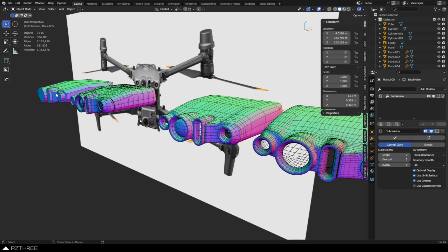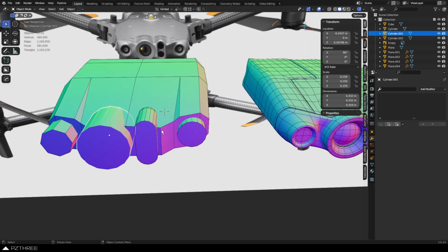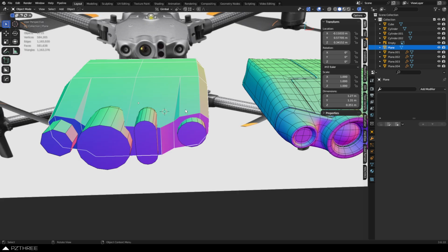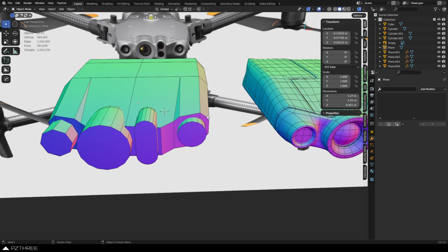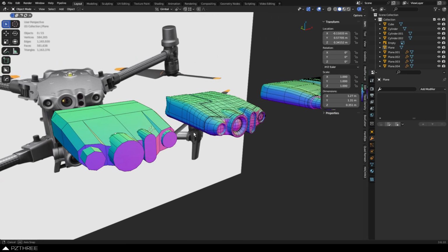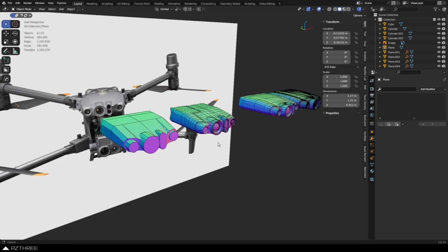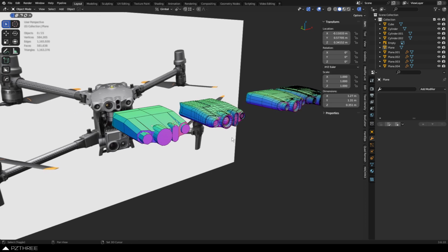That's what I'm getting at. Because you can see here, you can still do Booleans heavily to create these basic shapes, right? But if you're going to subdivision, you keep them basic. You don't make them all beveled and nice looking. However, if you're going to use a remesh workflow, you might just do bevels all over the place and high cylinder counts and all kinds of other fun stuff. That's a possibility, right? So the choice is yours on what you ultimately want to do with these types of situations.